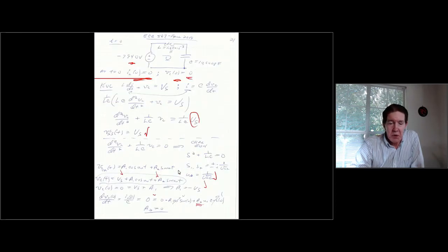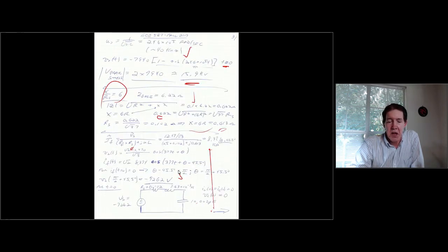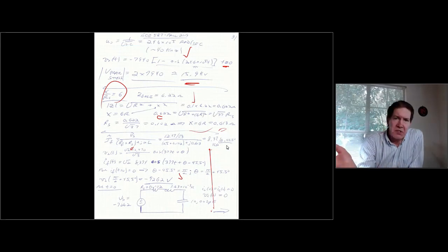So what this did is it shifted the fault current a little bit more. Before, we were getting minus 7,940. Now in this case we're getting minus 7,262. So it changes, again, by a little bit. But when I solve, again, when the circuit breaker opens, the fault resistance is out of the picture. But this time I've got resistance in the circuit due to the source resistance. Now I have an RLC circuit. And this time what I would expect to see in the solution is some damping.